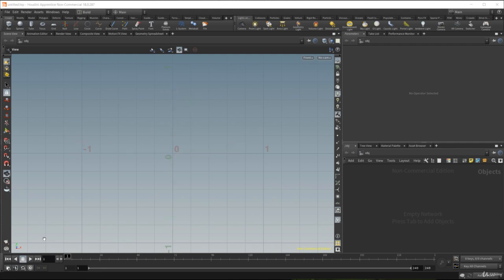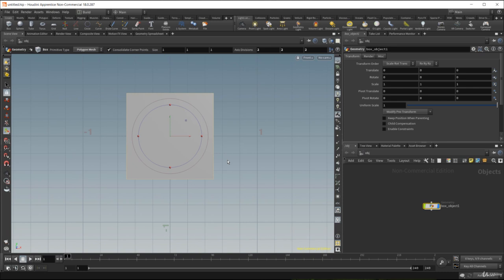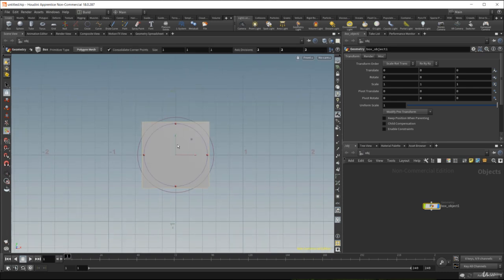We can also see that if you move to the left, x becomes negative, so the center of our world is at 0, 0. At the bottom here, y becomes negative as it goes down, x becomes positive as it goes to the right, and so on. So I can just press Alt Control and left click on the box, for example. That'll add that in my scene. I'll zoom out, and we can move objects around by simply clicking on these handles. Clicking on the Y handle will constrain it to the Y axis, which is up and down. Left click on that to move it up.